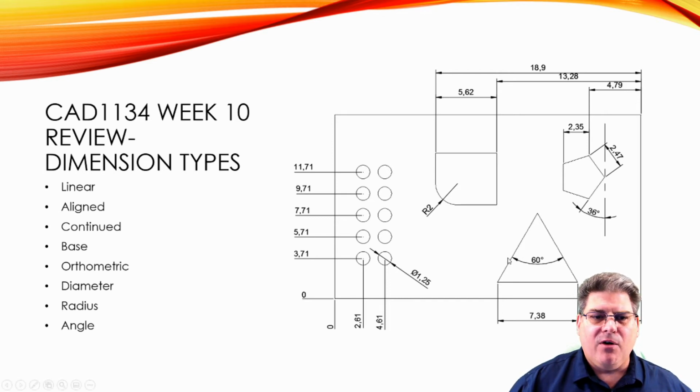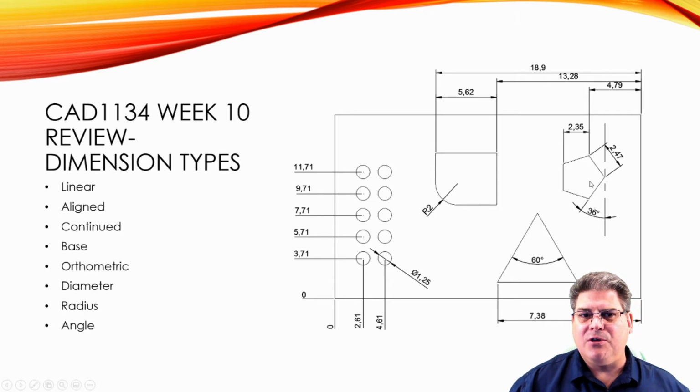An angled dimension can absolutely go with any other dimensioning style. Okay. And so here's an example. Here's another example where I'm dimensioning a geometric feature to a theoretical feature. So I have this phantom line here representing a vertical line, right? And I'm saying that this pentagon is 36 degrees canted. So feel free to do something like that.